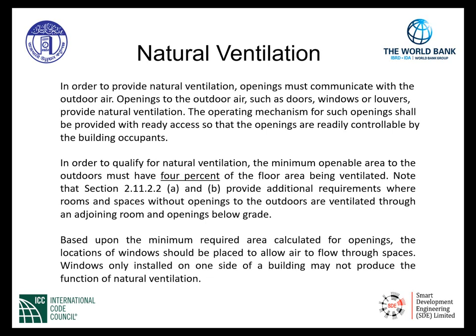Now, in order to qualify for natural ventilation, the minimum openable area to the outdoors must be 4% of the floor area being ventilated. Note that section 2.11.2.2 A and B provide additional requirements where rooms and spaces without openings to the outdoors are ventilated through an adjoining room and openings below grade.